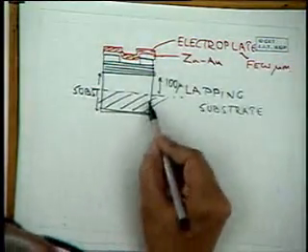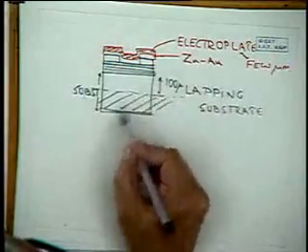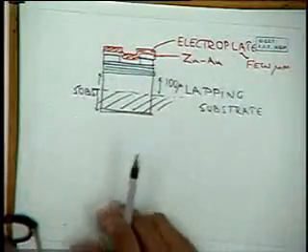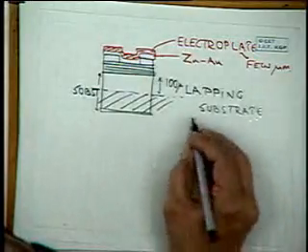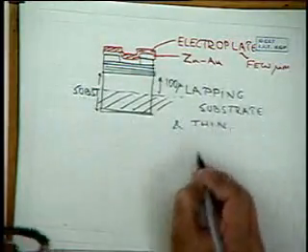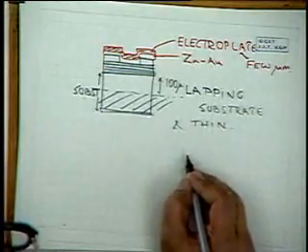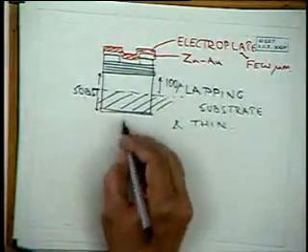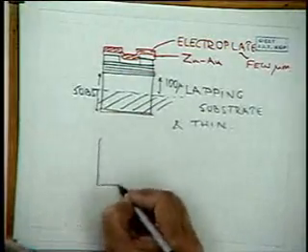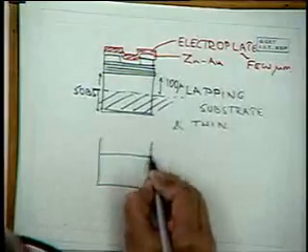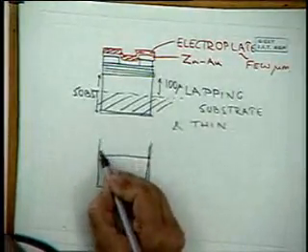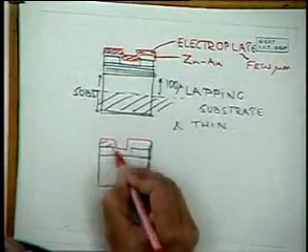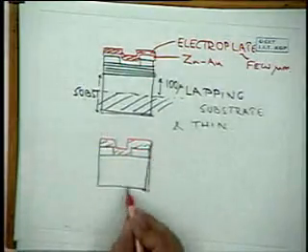And remember, this is the inactive side. This is just the back of the wafer, but it has to be done uniformly. You cannot do it at an angle, so it has to be done pretty carefully. So you thin to 100 microns. Then we are left with a material which is thinned, with the gold zinc layer. We want to make ohmic contacts to this.